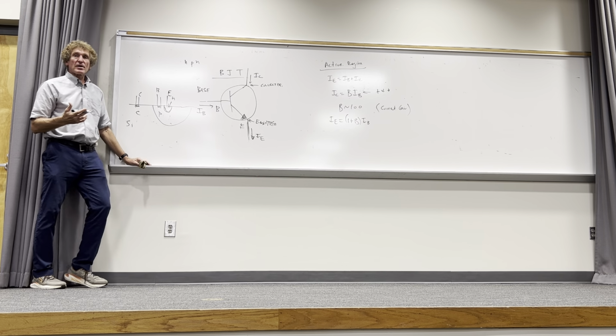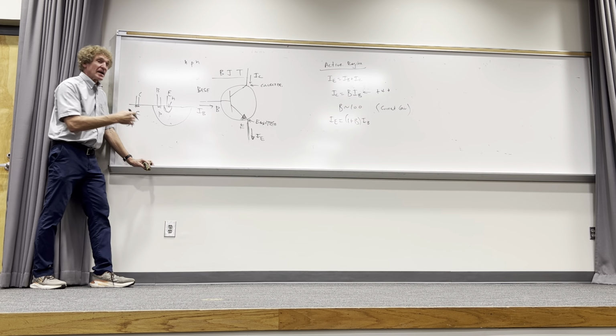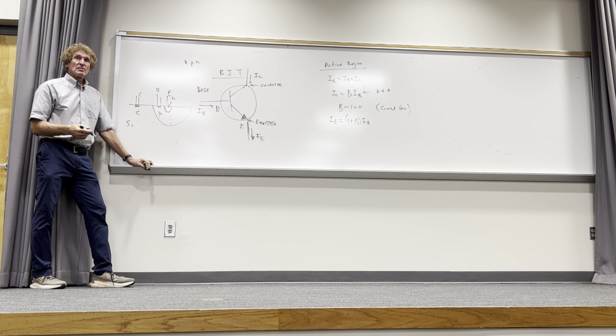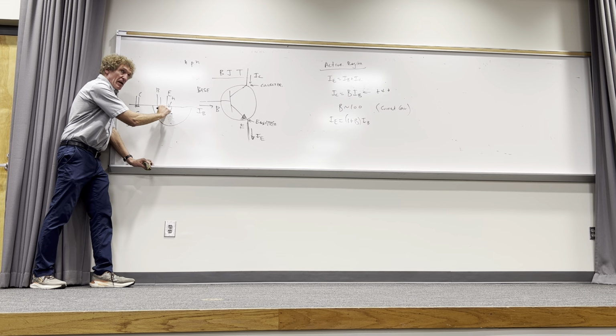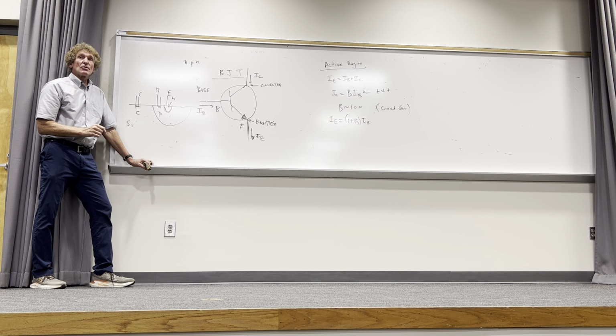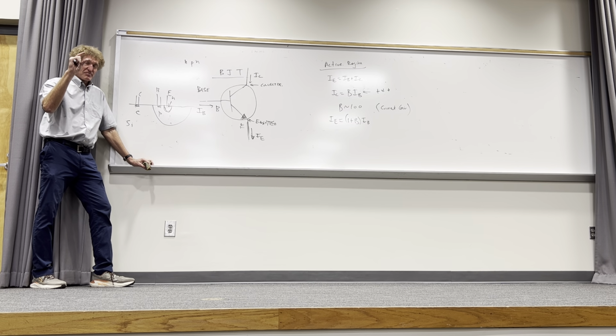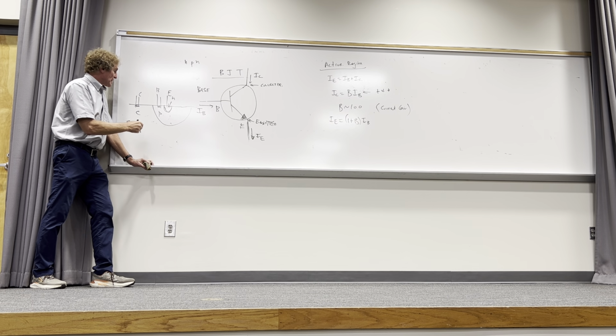Now, so how does it work? If I was explaining this to a bunch of high school kids who were, say, sophomores, I would say this. First, they have to understand the basic problem with PN junction diodes, that there's a natural gap here, where because of the way the actual band structure is, you're going to get a vacancy, a bare region there, and the only time you're going to get any current flowing is if you make this distance go to zero by putting a forward bias.